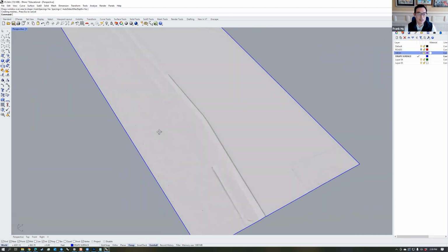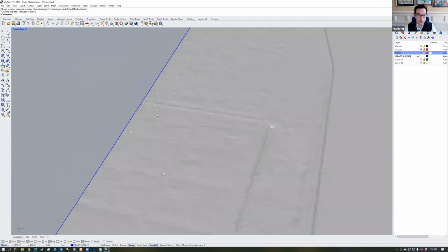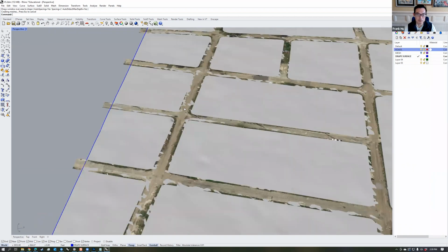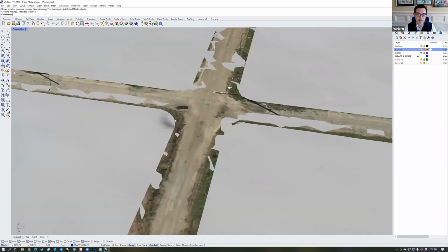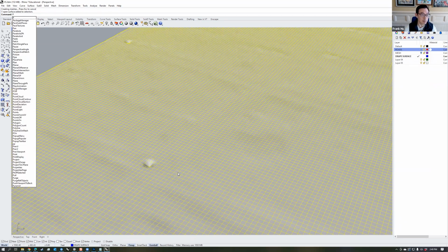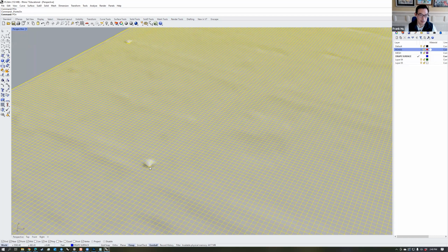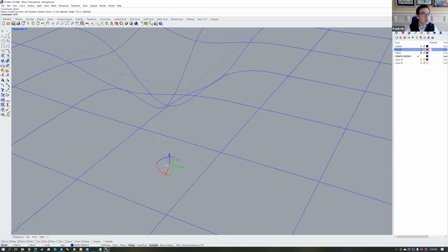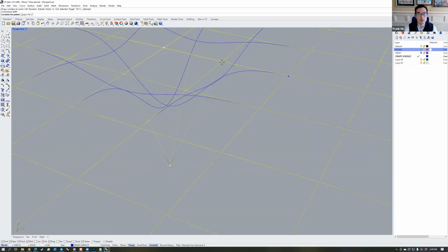And one thing that you notice are these little dimples in the landscape. The drape is looking for something to hit, but occasionally it finds a spot that's at the joint between one feature and another feature, and it actually just misses it. You can fix that by simply turning on the points for the surface. So PointsOn for points on, and then going in here, use the set point tool to bring it up to a nearby point.